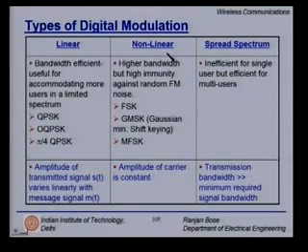In the nonlinear techniques, we have likes of FSK, GMSK, MFSK. GMSK is used in the GSM mobile phone standard. We will talk about it in one of the later lectures. And of course, the spread spectrum techniques, which are omnipresent in the 3G standards. Today we will focus on only the linear techniques, namely BPSK, QPSK, offset QPSK and pi by 4 QPSK.